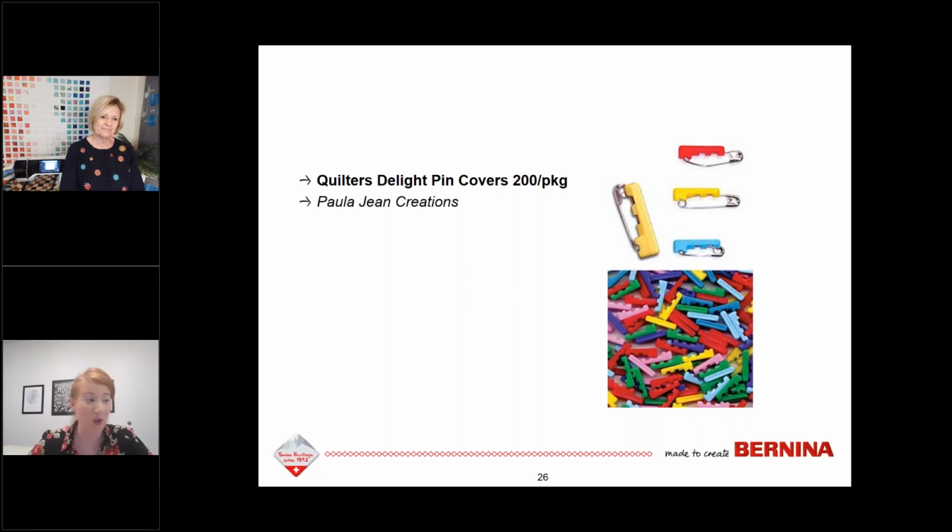We had a software question also. Can you remove securing stitches with the free BERNINA embroidery software? With the ArtLink software, no, that is not a feature of that software. As we showed in the early webinar, you have the stitch player, you have the ability to resize designs, stitch or print templates. But if you want the ability to actually edit an embroidery design, which we're really doing, you would need to go to the Designer Plus software.